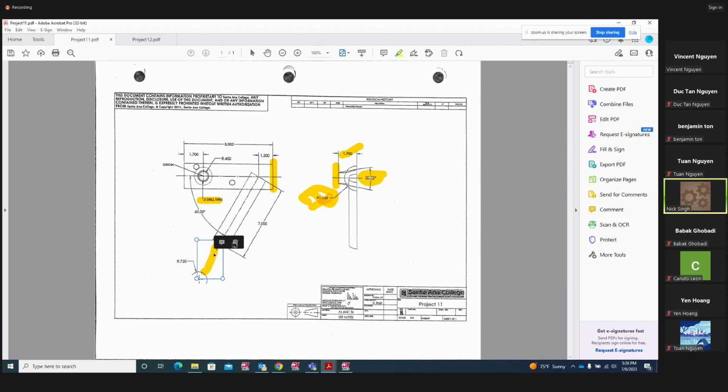Now we're going to draw this line here at Z0 on construction plane top, and that point is going to be from here to here. We had 6.3 minus 1.3. It's going to be 5 inches. So that distance from here to here is 5 inches. X is 5 inches.